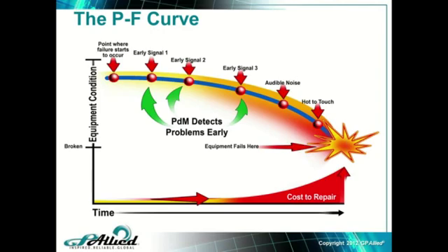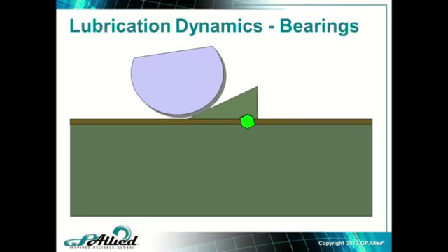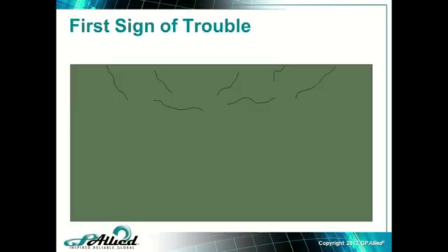When you're talking about things like those subsurface cracks, what's the minimum rotational speed that you could pick this up using ultrasound, vibration, anything like that? That's a really good question. That's a question we get a lot as well. I've personally done, the slowest shaft I've done is 8 RPMs, and in a race fault, just clear as a bell. And the slowest one I've ever seen presented at a conference was 1/3 of an RPM. Okay. So in essence, there's really no lower limit.